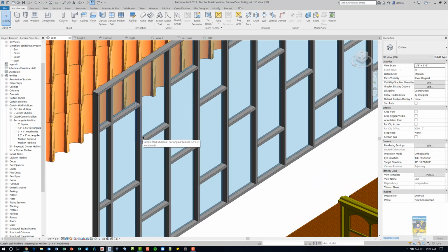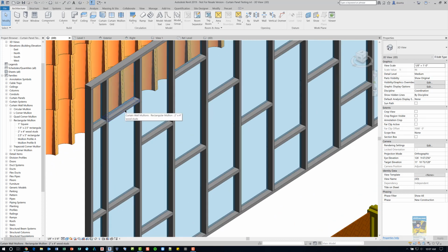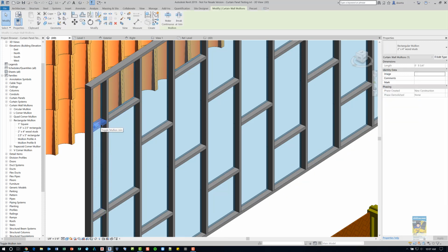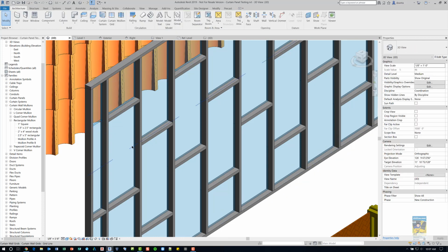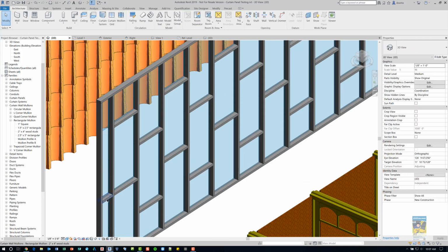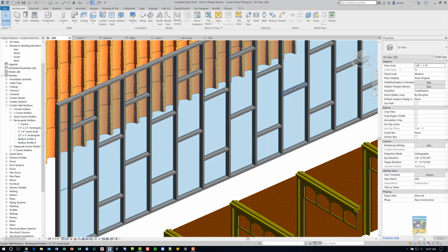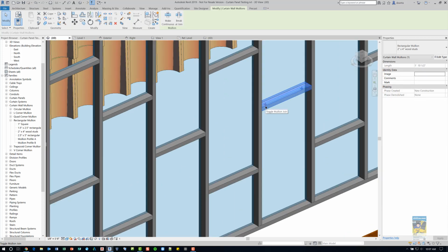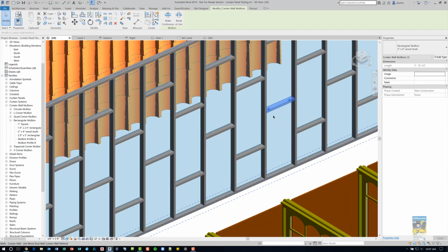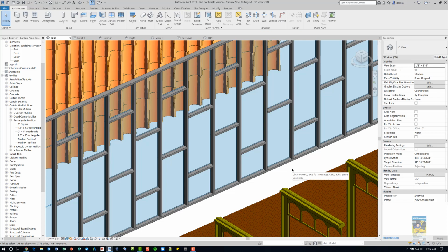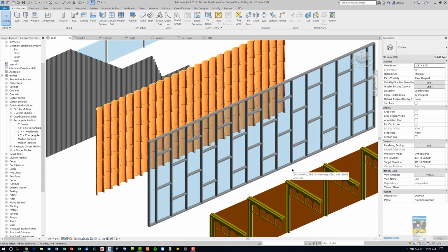Now, using this method, however, for the horizontals, you'll notice that it draws them across all of them. And so you may need to take certain ones that you have, and you may need to delete them. So for example, here, if you're trying to create a staggered type of situation, you can delete the ones that you don't need. The good thing using this method is that you can still click the toggling of the mullion joins so that they can go through if you want the horizontals to go through, or leave them the way they are because as it stands now, the verticals are continuous.